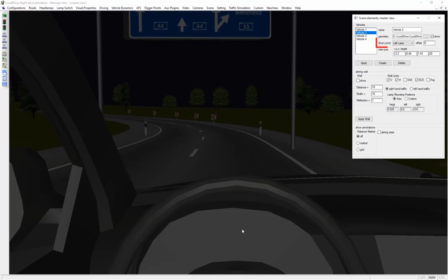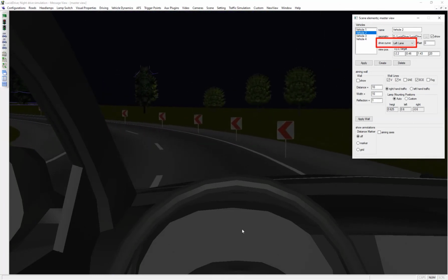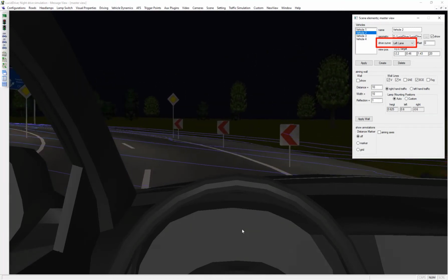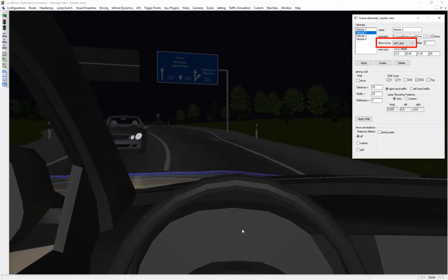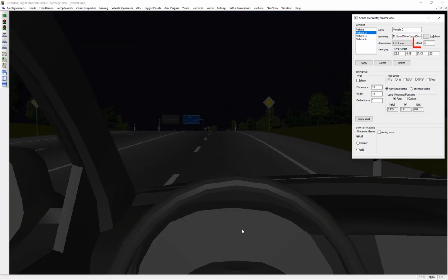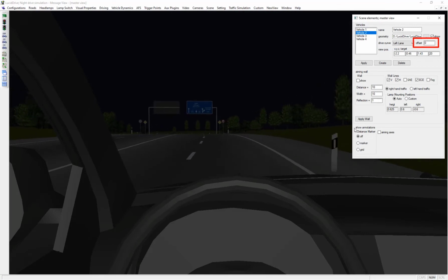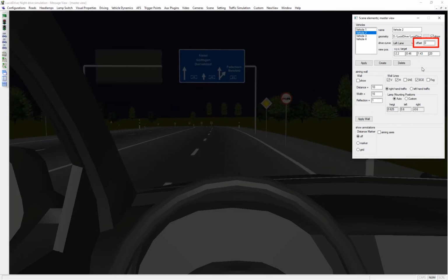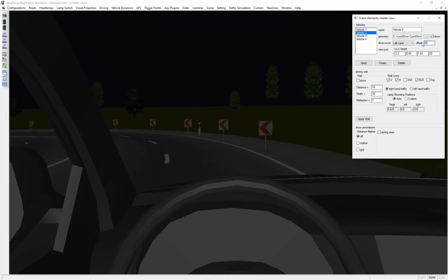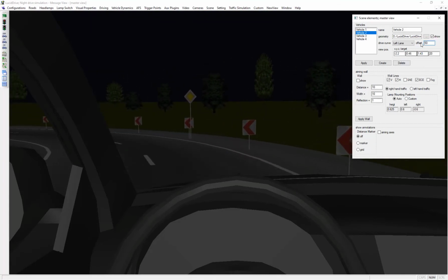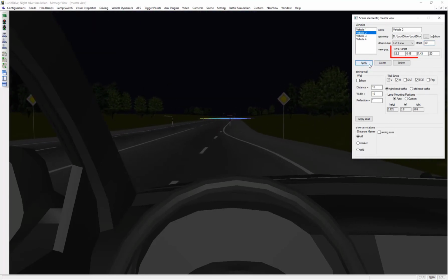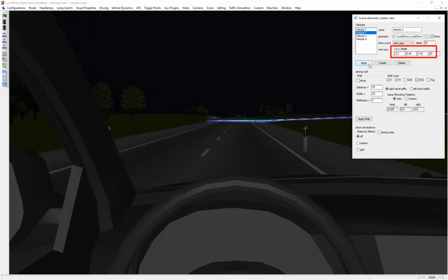On the right of the dialog, you have the option to specify the position of the selected vehicle. You can use the pull-down menu to determine the driving lane for the vehicle. We will keep left lane. The parameter Offset allows you to move the vehicle from the default starting position. Enter 50, to move the vehicle 50 meters along the road. Click Apply. Furthermore, here you can determine the driver perspective position.